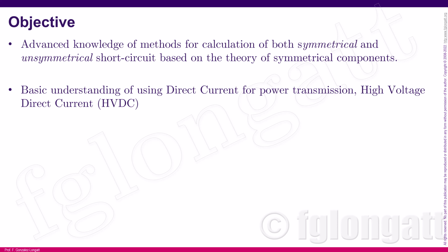In this course, I will start talking about abnormal conditions, then I will define a fault, and from the concept of fault, we will classify the faults in shunt faults and series faults. Please be aware that the general name is faults, but we have different type of faults. Series faults that they are typically known as open circuits, and shunt faults that they are the short circuits.